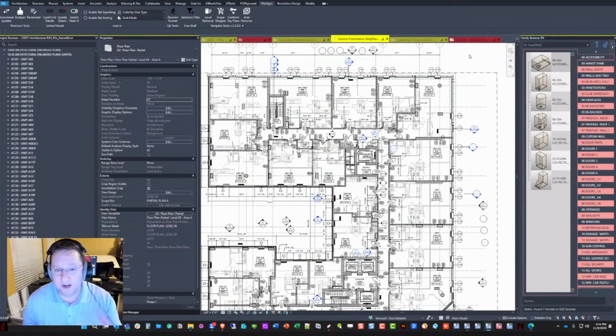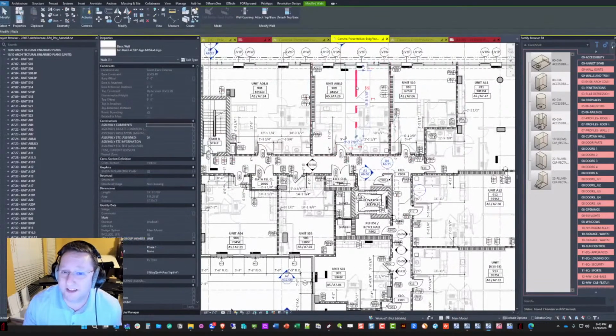I'm sure any of you who use groups as much as we do know that Dynamo has an Achilles heel when trying to edit groups, in that it really can't. It'll just break the groups apart. However, text parameters that are set to vary by group instance can still be edited if those elements are in a group, because you don't need to go into the group context to edit it. So this is a parameter that I can edit right now on the fly. It's not going to break the group at all.